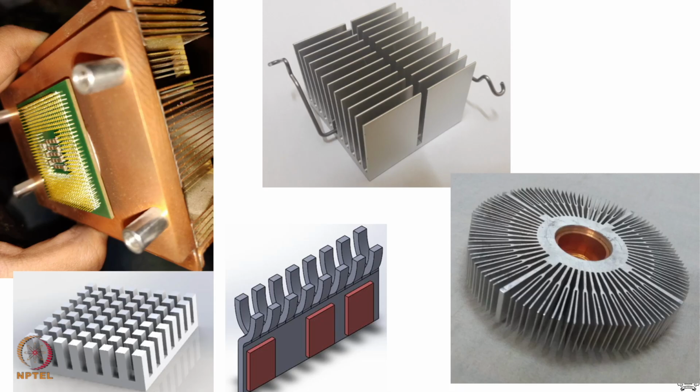This is a heat sink that is shown here. The flow inlet goes through this and exits on the other side of the page, and a processor is mounted. This is the substrate, and these are pins that go into a socket, and this white color is the thermal interface material that bonds the heat sink to the package here. And these are some squares cut